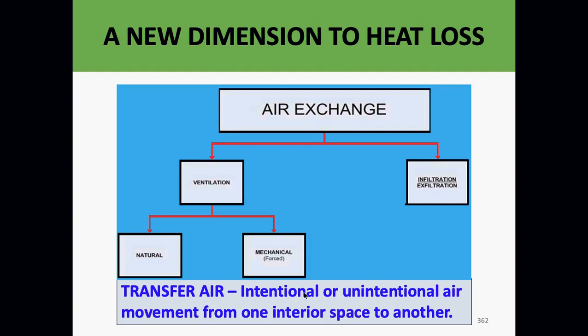Transfer air is either intentional or unintentional air movement from one space to another. It's not outside yet. Transfer air is just movement of air through ductwork or through stack effect from one space to another. Ventilation is intentional. We want to ventilate.